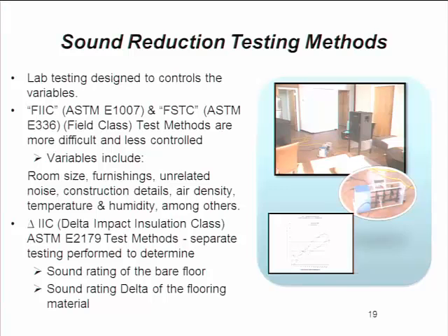All of that is controlled in a lab environment, but relatively uncontrolled on the actual job or field site, because in many cases they may not have all the windows in, or they may not have the air conditioning working. It may be hot or sweltering. So all of those on the field will have some impact on the resulting test. The IIC is the test, or the delta, to try and separate the membrane performance itself.